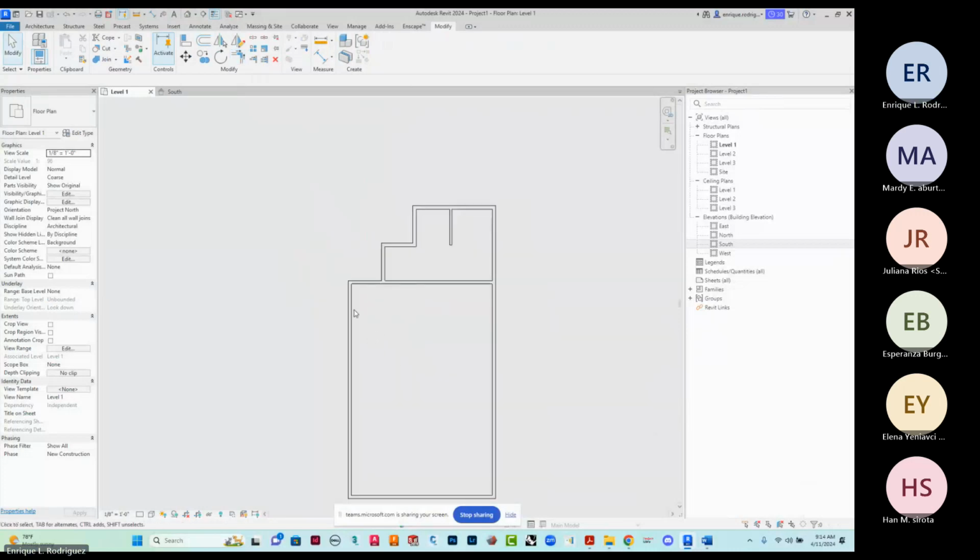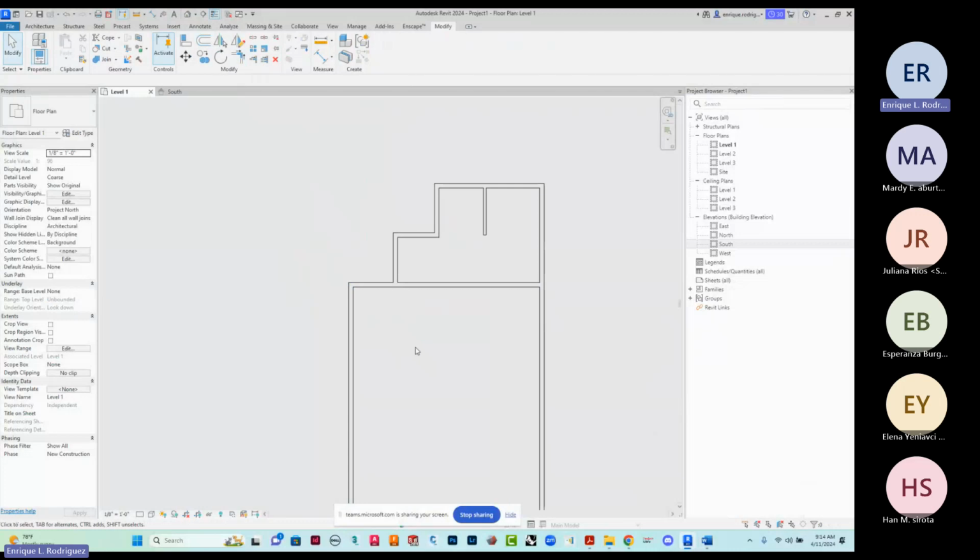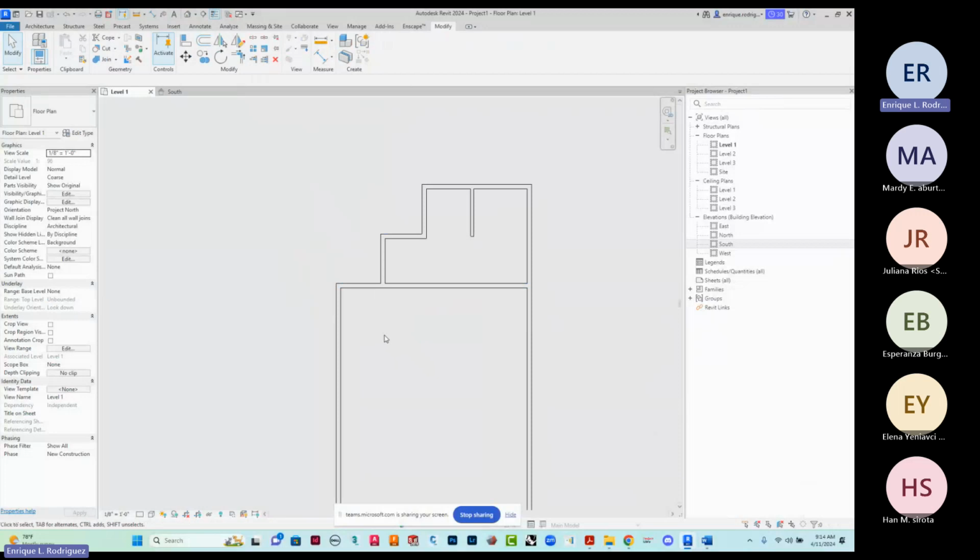All right. We talked about this being a generic 6-inch wall coming across right in here. In reality, what you're going to have is a condition where you've got an exterior wall in here that converts to the inside in here. Now, if this is an entirely bearing wall, more than likely the core requirements of that, which is your stud and the stud spacings, is going to be the same. But what's going to be different? Well, the difference is that this is probably going to have a different finish. The composition of that wall, other than the core, is going to be different.